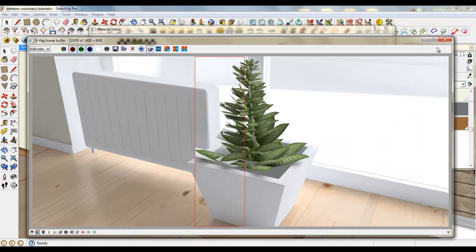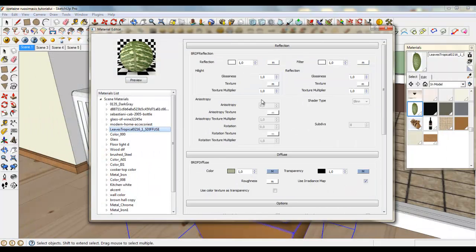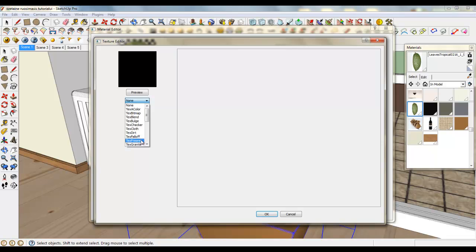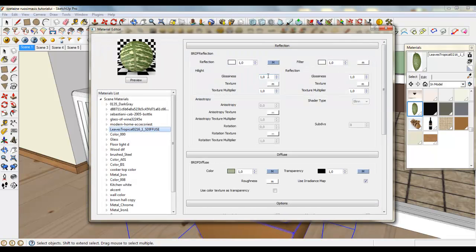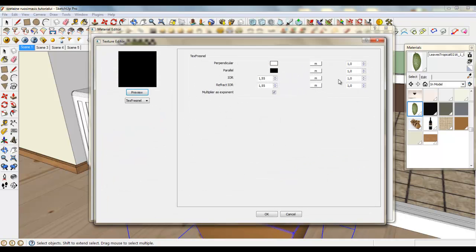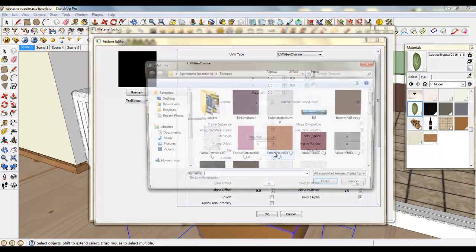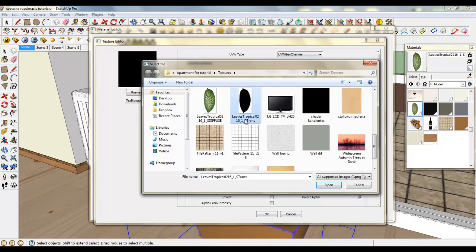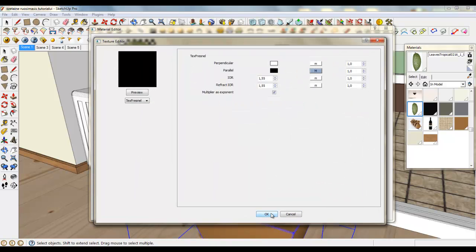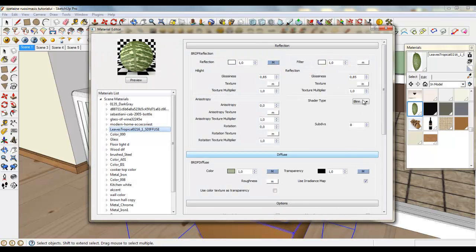But also we need a reflection. So go to create reflection, add the Fresnel map, leave everything, type in 0.85, and also we need a reflection map on this bitmap file, and also place the same map and choose Phong. This material is done.